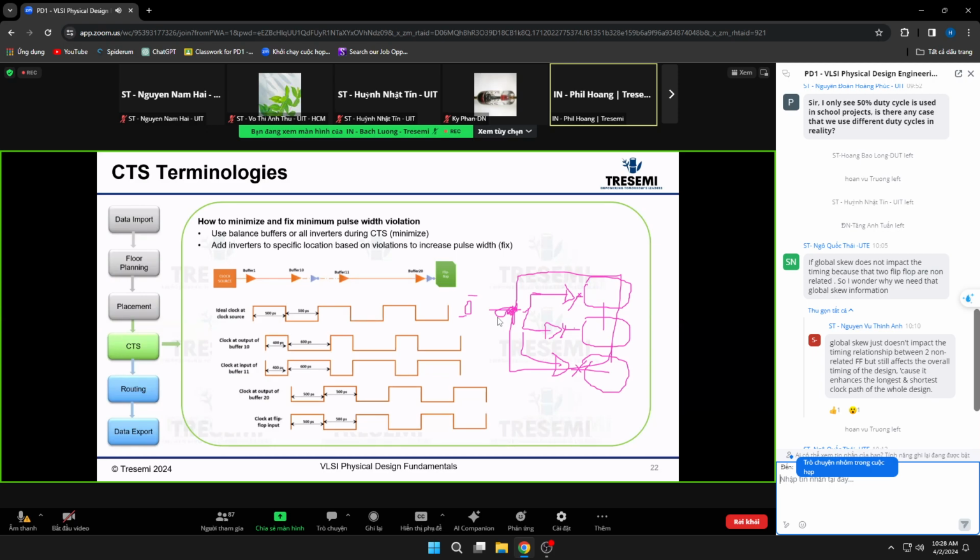If you do it manually, you run the risk of not modeling the clock correctly, because you're creating virtual clocks over here, but in reality it's only one source, with a physical crystal oscillator, or you have an on-chip PLL that only drives one output.